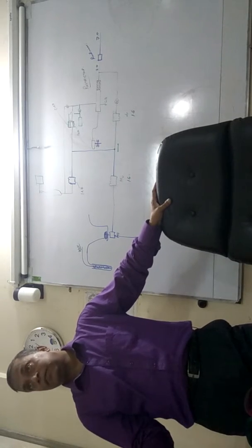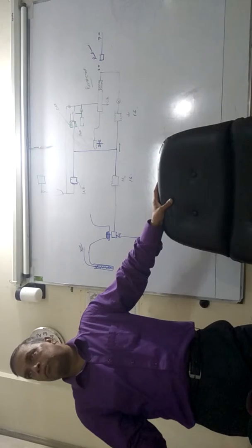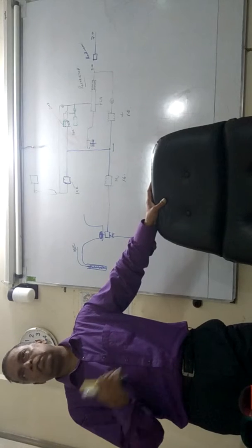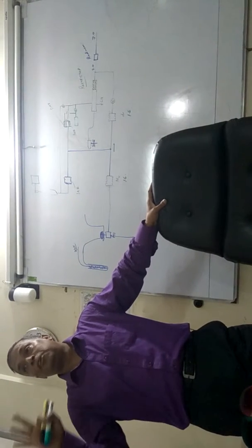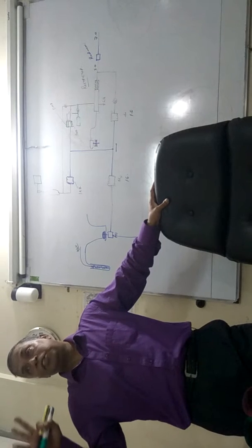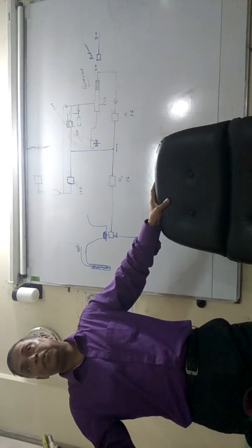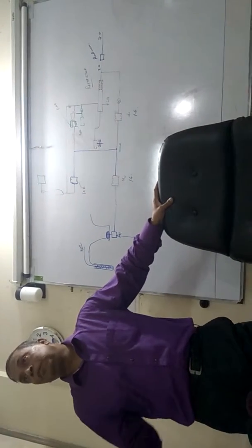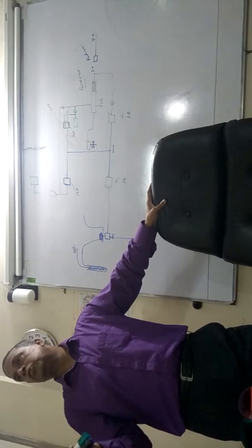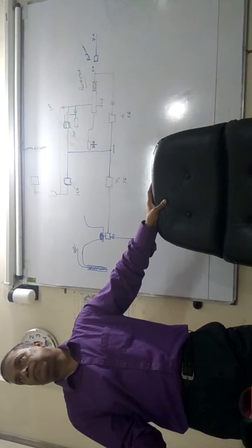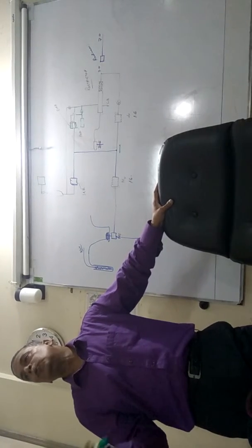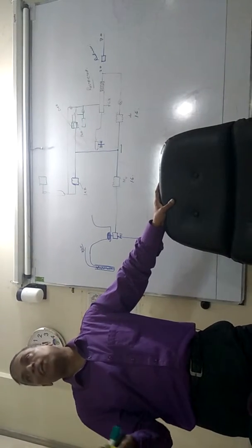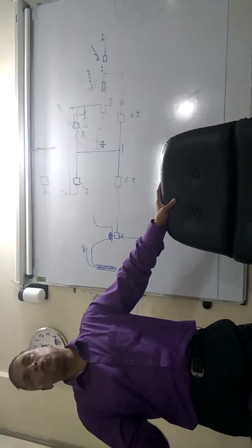Okay, offset. Another term used is error. Error is also the difference between the measured value and desired value. So there are three terms for deviation. Deviation itself is a term, then is error, then is offset. Offset is a classic problem with simple proportional control systems. Okay, and to remove it, to correct it, an integral action is required, which we will be learning later.